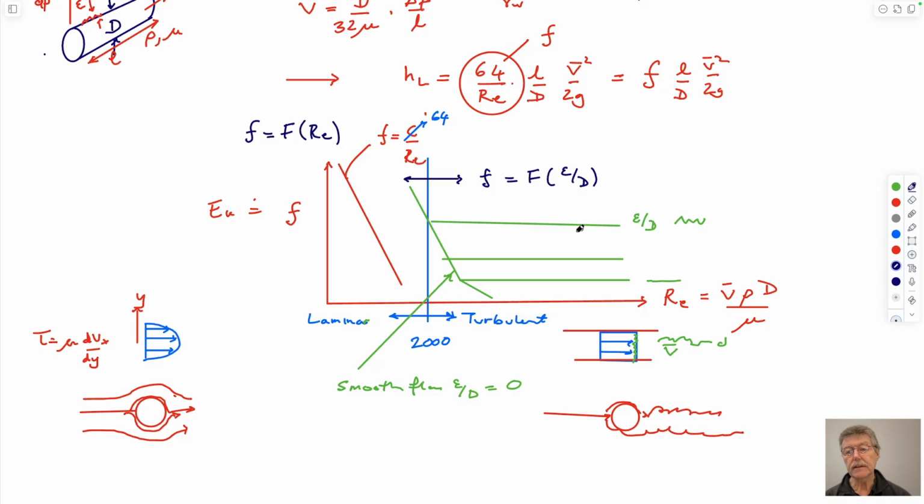And so that is interesting. It means that this characteristic flow between laminar and turbulent exists for external flows. If you're flowing around a plane, essentially the same chart exists. It also exists for open channel flows, flowing in a river or in a ditch, where you go from laminar flow to turbulent flow. It's indexed by Reynolds number, always.